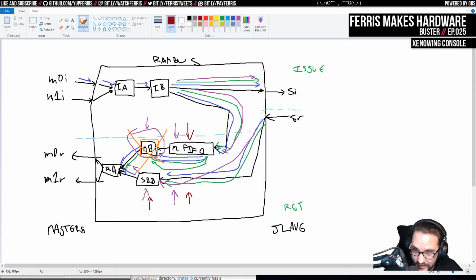And if this arbiter tells the FIFO to get data, that data is not going to come back until the next cycle. So I think that behavior where we want to output the data, the arbiter needs to do that. And then if it would watch 2 FIFOs, then I think we're okay. Because then data comes in here, and then a cycle later data comes into this FIFO. And as long as there's data in both FIFOs, then we can issue a read to both.